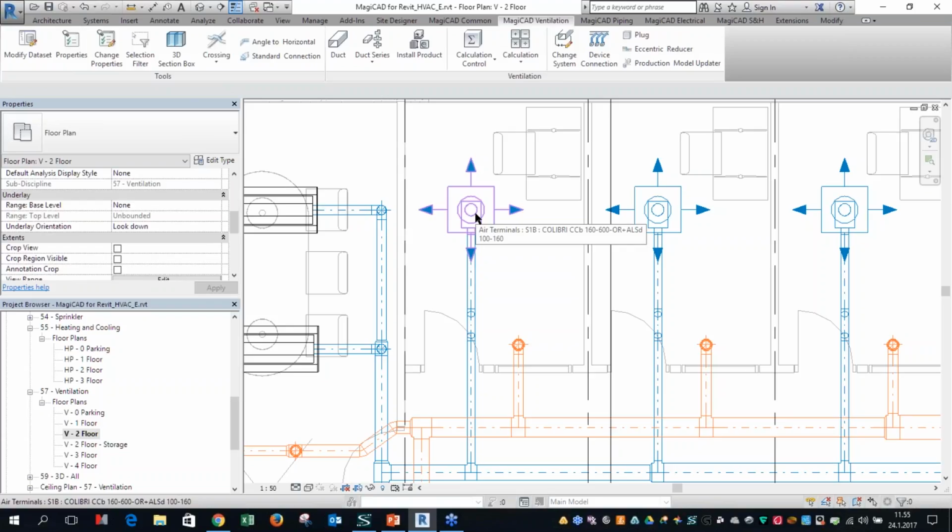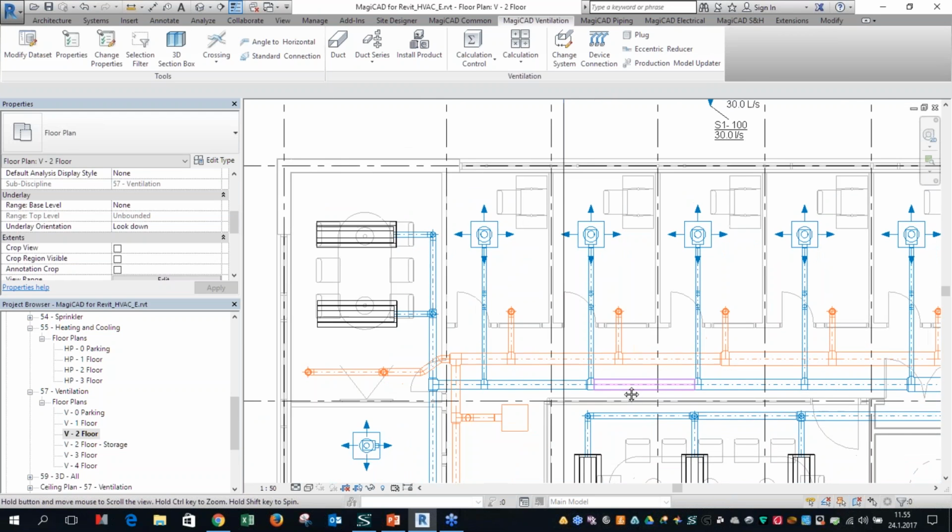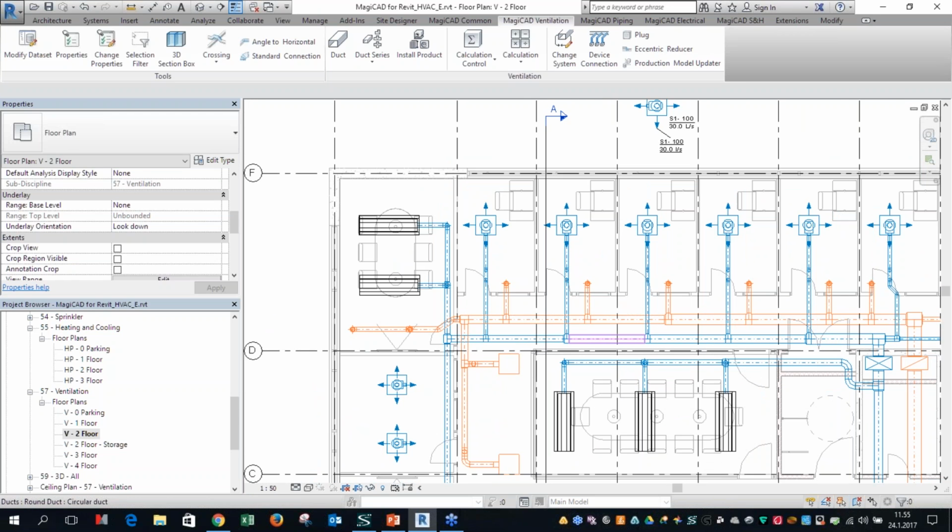Or not only pressure drop, you can also define the K factor or K coefficient for the sprinklers. And of course, you can define the flow, but that worked already earlier. But just so you know, if you have your Revit families, now you can define the pressure data, and MagiCAD calculation is able to use it. So it makes this Revit family support, MagiCAD family support, even better.